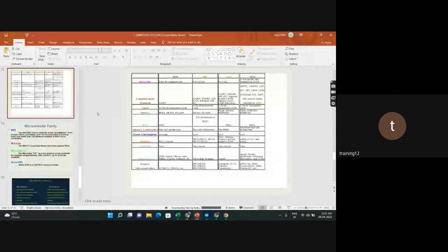Then memory architecture. In the 8051, Harvard architecture is used, and in PIC, Harvard. AVR is modified Harvard, and in ARM also modified Harvard architecture. Then power consumption: in the 8051, power consumption is average. In PIC it is low, AVR low, and ARM low also.